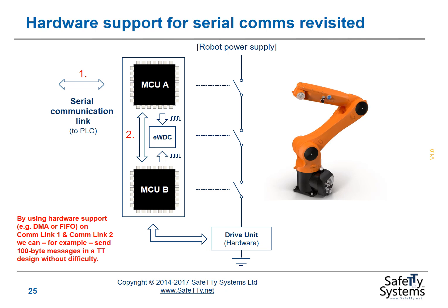So we might use, for example, a UART-based communication link with DMA support to allow us to send 100-byte messages between MCU A and MCU B, for example, and the arrival of each 100-byte message on MCU B would drive the scheduler on this node.